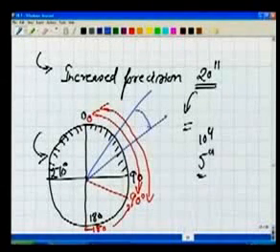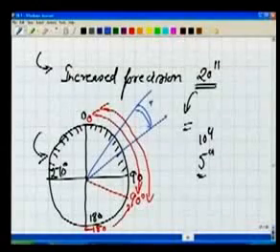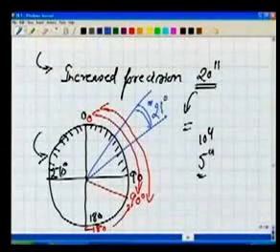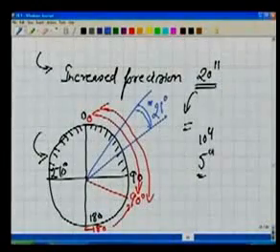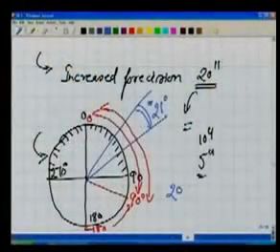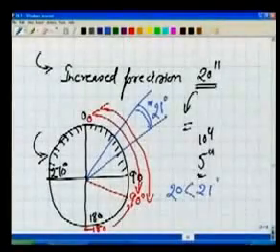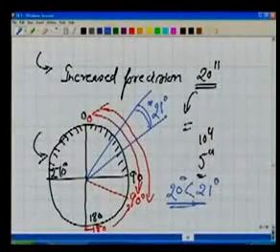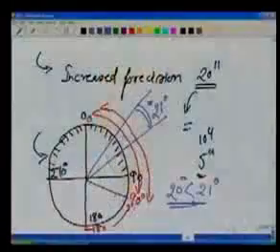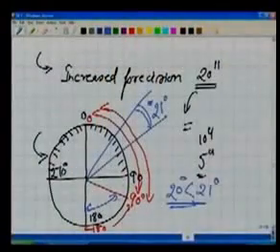So the actual angle value is, say, 21 degrees, what will we measure? We'll observe it in the theodolite slightly less than that. Let's say 20, which is less than 21. Why? Because these graduations are far apart. Similarly, in this part, if we are observing, we will be observing a smaller angle to be larger.